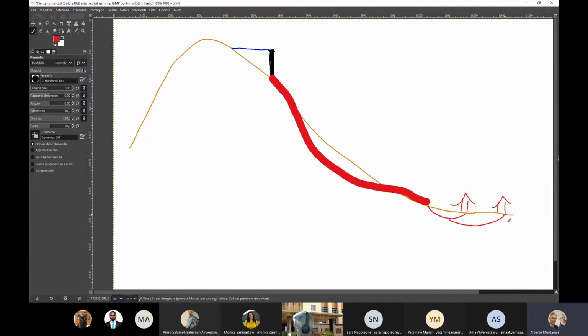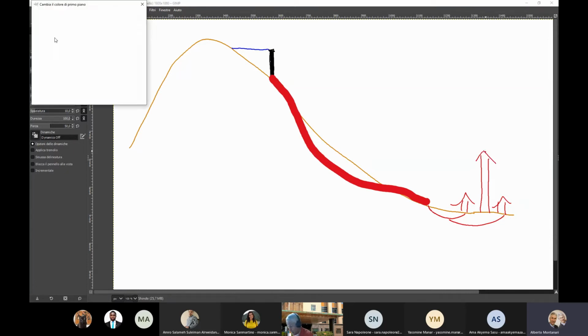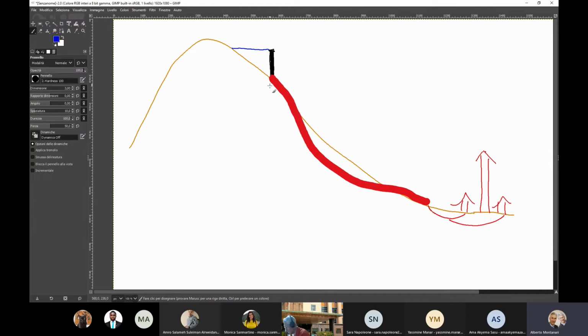Okay, first of all, you want to keep the energy, because let's suppose that you have a very high skyscraper here. You want water going up to the skyscraper. So you have the water that is going down here and comes to the pipe. And you want the water reaching the top of the skyscraper. So you need pressure, because if the water has no pressure, it doesn't reach the top, and you need to put pumps in the basement of the skyscraper. So you want to keep the pressure, and you use a pipe.